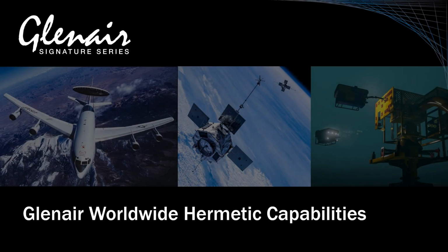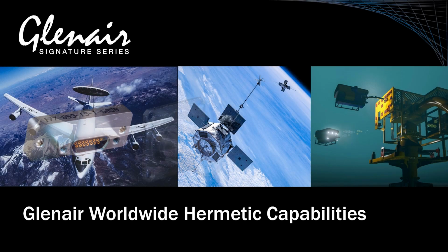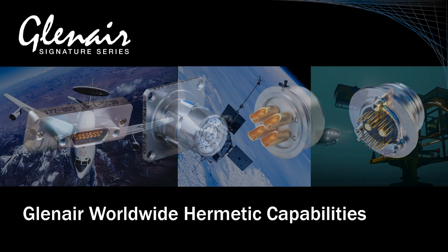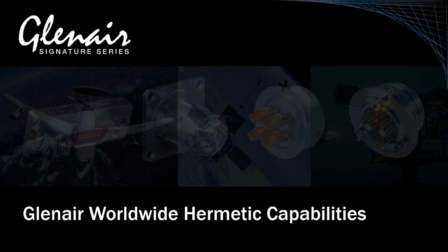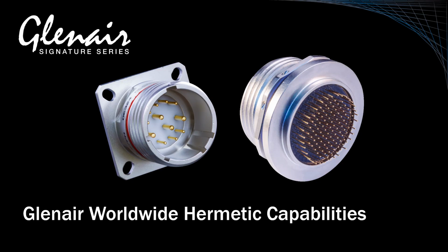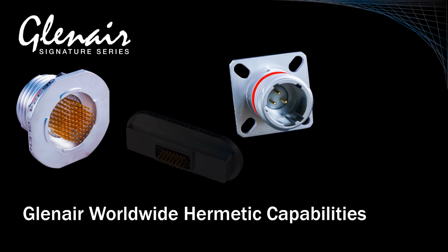Hermetic seal connectors are used to resolve potential gas, moisture, and particle ingress problems in high-pressure, high-altitude, and vacuum barrier applications, to prevent moisture and other contaminants from damaging sensitive electronic instruments and equipment. Hermetic seal connectors produce a condition commonly referred to as air tightness and are fabricated via a glass-to-metal or lighter-weight encapsulant-to-metal sealing process. Both technologies deliver outstanding airtight performance for high-reliability applications and may be specified in a broad range of both circular and rectangular connector packaging.